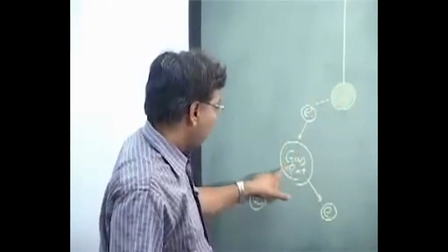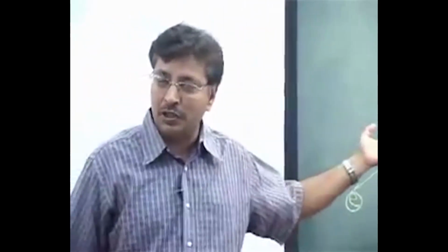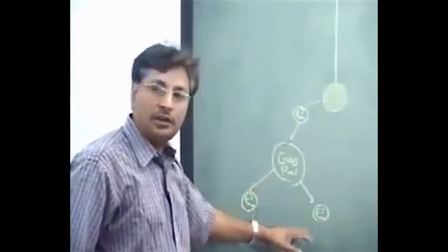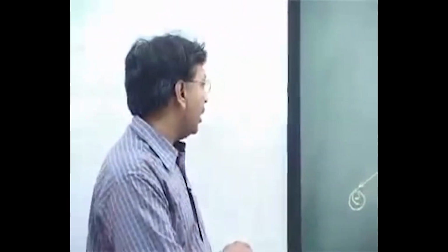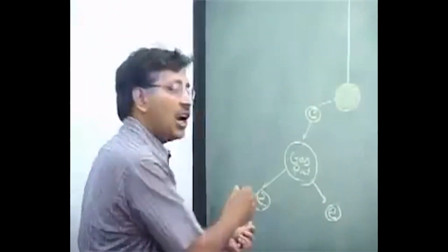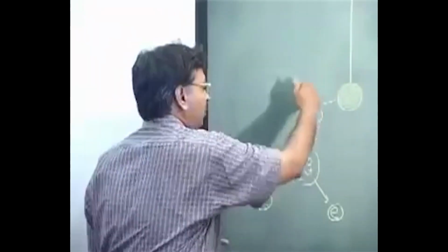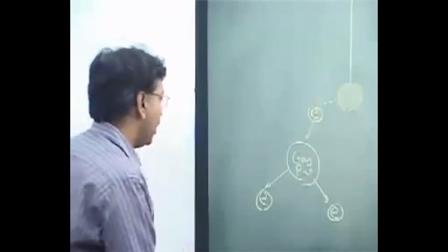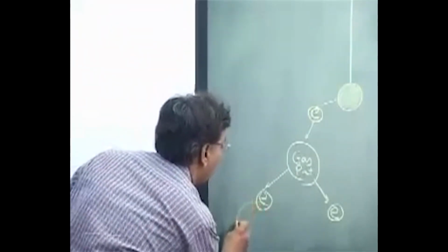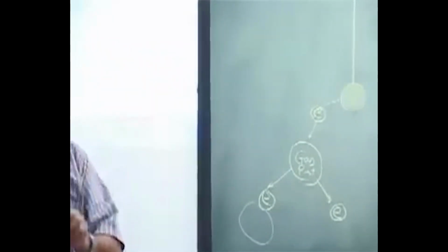These gas particles will become positively charged, and they will rush towards the electrode and get discharged. But the electrons which got free will continue to move away, but their energy will reduce. Once their energy is reduced, they cannot do more charging and knocking off of electrons from the gas particles as we go away. But in this area, they will do a lot. Once these electrons become freely traveling and encounter a particle or dust, they can sit onto the dust particles.